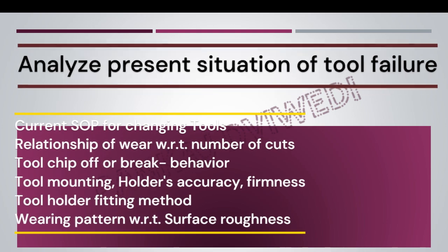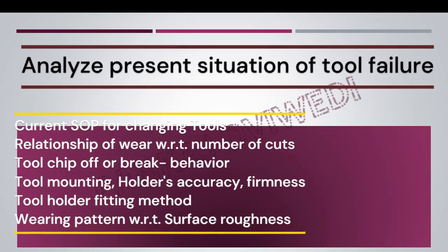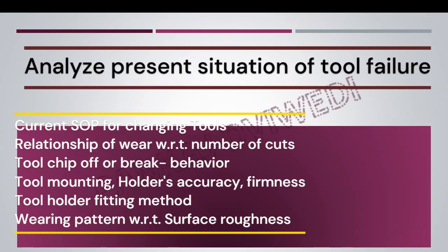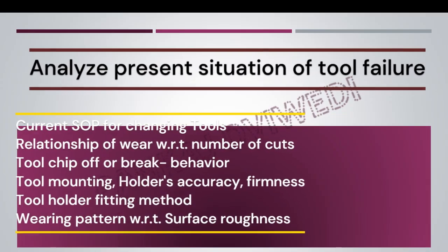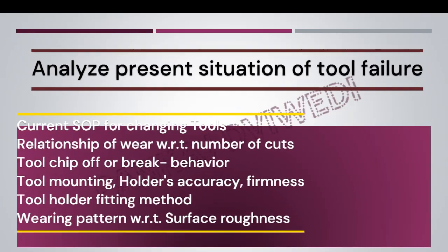Record whether the tool is breaking or wearing out, and what is the frequency of that breakage or wear. You need to record a minimum of 3 days of data and analyze the mounting of cutting inserts, tool holders, their firmness, their rigidity, and their accuracy.